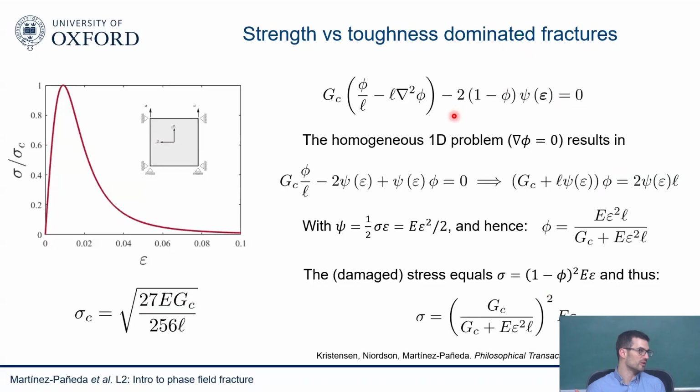This is what engineers normally will do before phase field, or they still do, when they are looking only at crack initiation. They will calculate G or K, the stress intensity factor, with a stress analysis, and they will then compare, and that will tell them whether a crack will initiate or not. Here I can model crack initiation and propagation just by having that G idea embedded into the phase field equation. So I don't need to calculate anything. I'm just solving this equation. I'm not doing anything extra. I'll show you later how to do it.